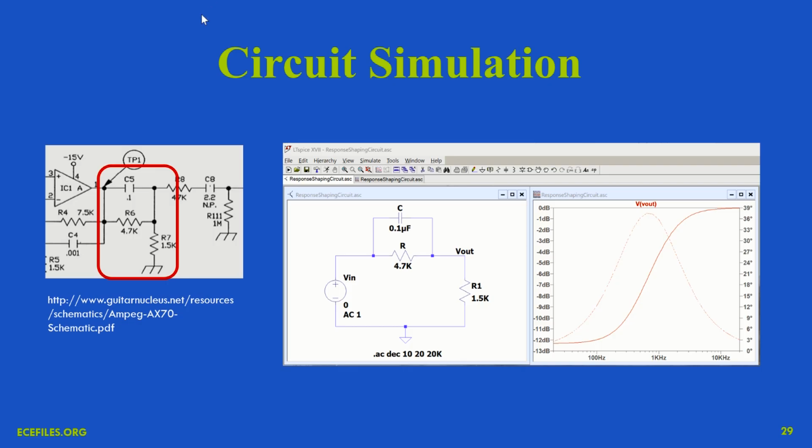Well, one way to answer that is to just do a quick circuit simulation. So here's the circuitry we're interested in. Remember, it's at the output of an op amp. And as we said in previous episodes, we can ignore the complexity of everything circuit-wise that's to the left of this point right here. Why? Because this is a low impedance output. It just looks like a voltage source. So that's my Vn here in this circuit simulation.